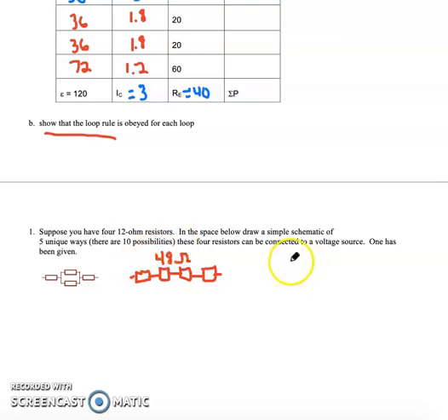And the other more obvious one is if I put them all in parallel. So I could have 1, 2, 3, 4, right? Connect them in parallel. And the effective resistance would be not 12 plus 12 plus 12, but 1 over 1/12 plus 1/12 plus 1/12 plus 1/12. Or the shortcut again would be I have 12 ohms divided by 4 resistors, so the effective resistance would be only 3 ohms. So this gives you the maximum possible resistance for 4 when they're in series. This gives you the minimum. All the other combinations will give you somewhere between these two.